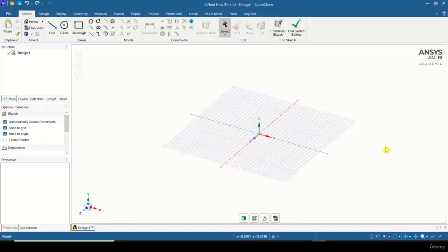It must be oriented in that way. Or if your pipe is standing up, then it will be parallel to the Y axis. So it depends on the orientations and every aspect of the domain, like in what orientation your pipe is fitted in the system. All those things you have to consider and orient in that way, so that you can replicate the real physics of the flow or the system you're planning to simulate.